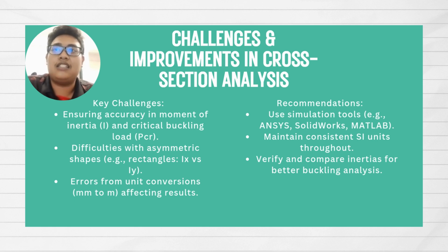Today I'll be explaining challenges and improvements in cross-section analysis. First, key challenges. Ensuring accuracy of the moment of inertia I and critical buckling load, PCR. Difficulties with asymmetric shapes, for example rectangles where Ix versus Iy. Errors from unit conversion to meters may affect results.